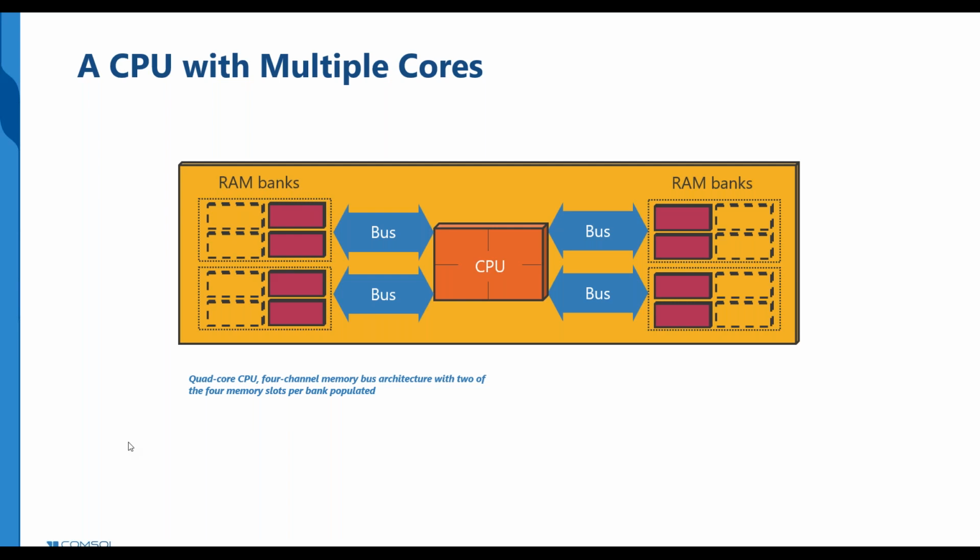So I wouldn't say that choosing the number of cores and the coarser mesh is in any way in conflict with each other. They are very different, and using cores is basically for free with COMSOL. You don't pay anything extra for using all available cores. So I see no reason why you should not use the maximum number of cores. The only reason I can come up with is the memory effect, that you will use a little bit more memory for it. But there are two very different questions.